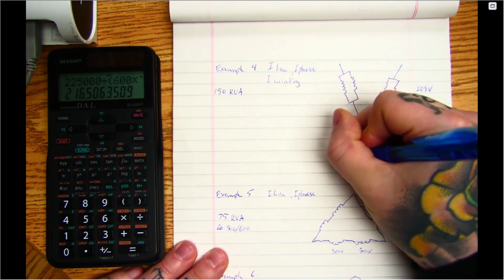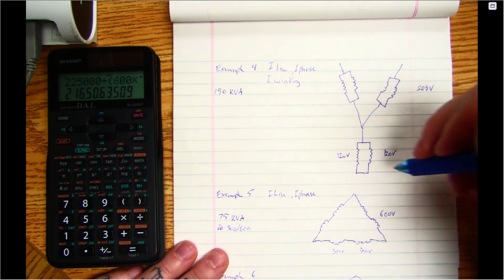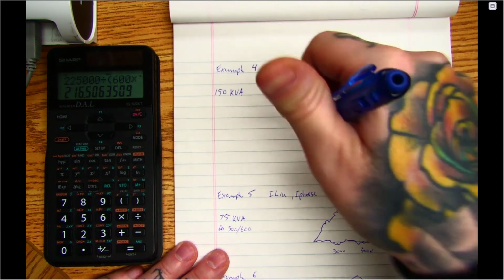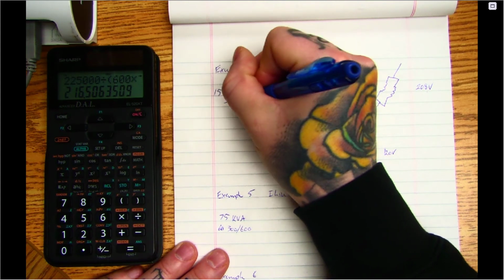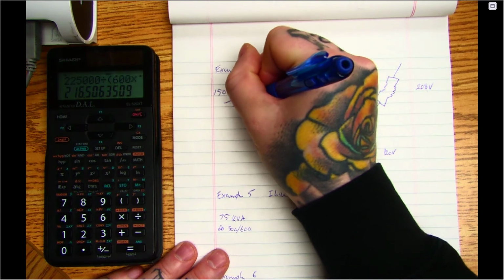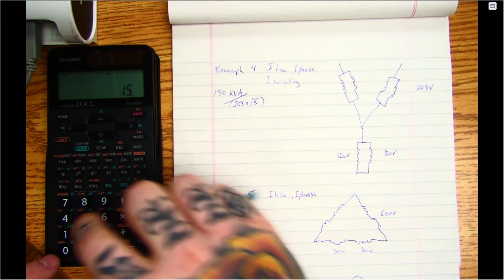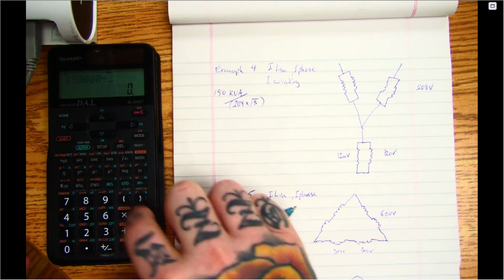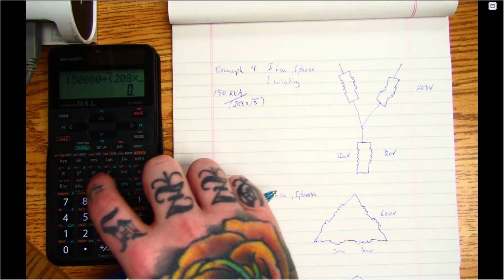So that means I have 120 volts on both these windings because they're in parallel. I want to find out the line current and the phase current. So I'm going to use my line voltage with my kVA. In this case it was 150,000 VA divided by 208 times root 3. So I get 150 divided by bracket 208 times second function root 3,